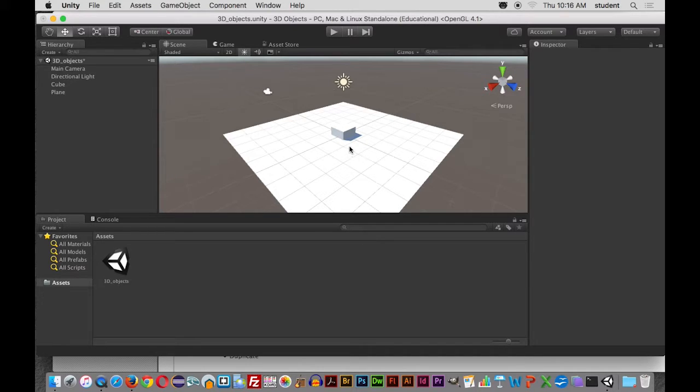Okay. And the reason I'm having you do that is so that in a few minutes, when I show you how to navigate within there, we're navigating in a global view, meaning everything will be centered. Everything will be navigated through that 0 point on your scene view, okay? Not on the local scene view or the local object that may be selected.